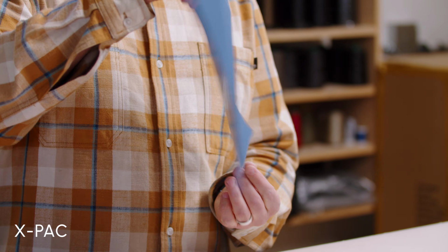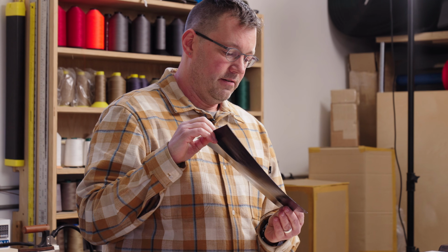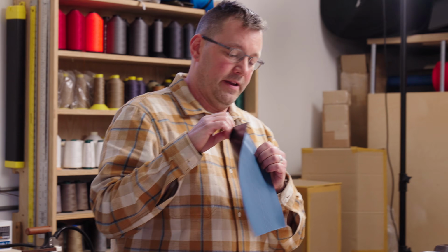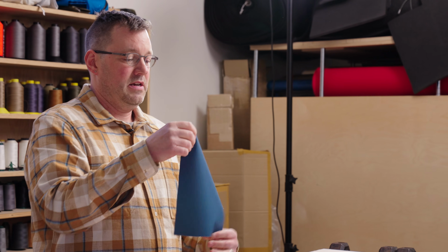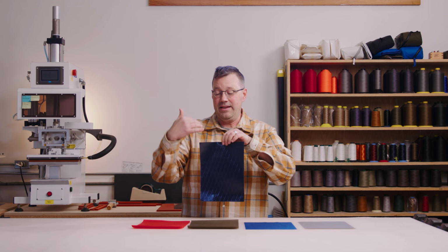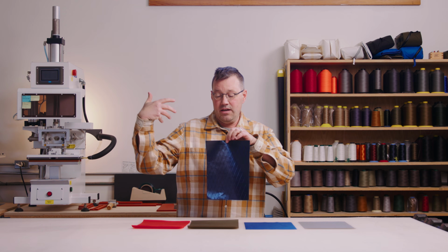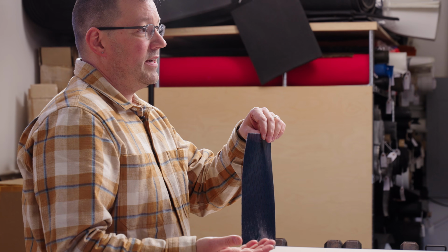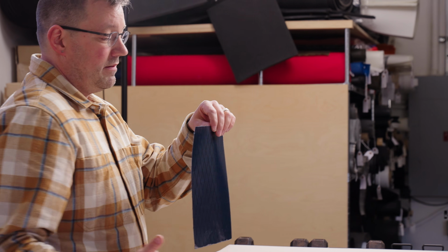We're doing some collections with X-Pac, and this is a composite material. So we use X-Pac X42. The face of this is a 420 denier nylon. It is not balanced woven, but plenty durable and abrasion resistant. So this is a composite, it's 3 layers. Inside, the next layer is what they call the cross ply. These are polyester yarns that are laid in a kind of diamond direction. This concept or technology comes out of the sailing industry. The purpose of these yarns is to stabilize stretch in the bias direction.